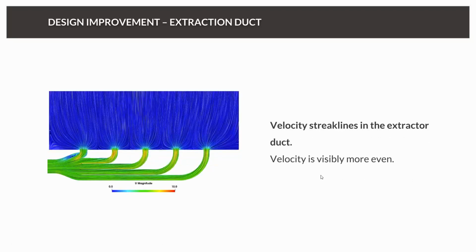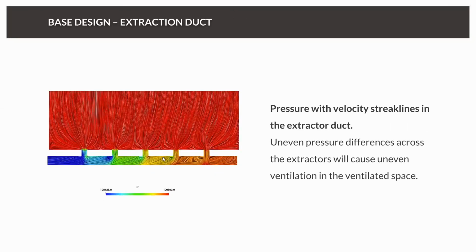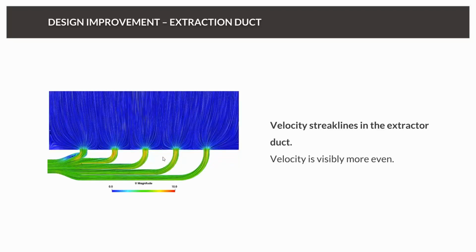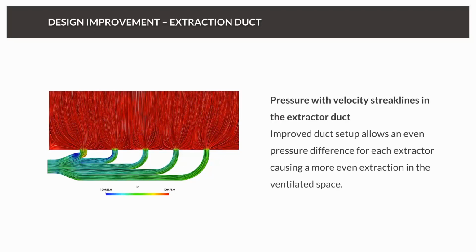And if we now improve the design, so we use these parallel ducts with different radii and a different curvature, we can see that it's much more homogeneous, and we actually have the same fluid velocity of around 5 meters per second at the outlet for all 6 or 5 outlet locations.